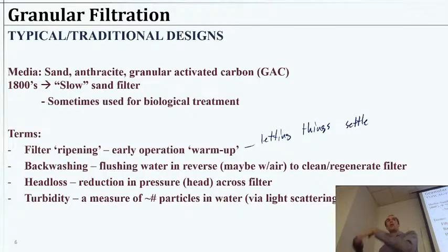It's going to use this much water, and so on. So for granular filtration, that's the design key: to manage, okay, we're producing this much, but we also have to use some of what we produced to backwash, to operate in this efficient manner. So it's going to waste some water, aka send it to a wastewater stream to be treated, but overall it's a very good process. It's cheap otherwise and reliable.